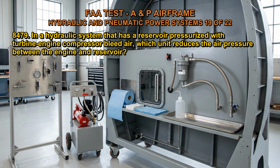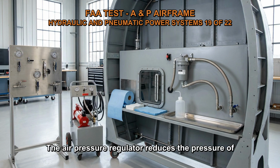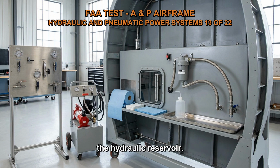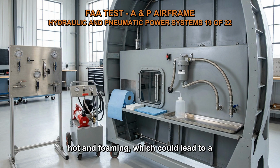8479. In a hydraulic system that has a reservoir pressurized with turbine-engine compressor bleed air, which unit reduces the air pressure between the engine and reservoir? A. Relief valve. B. Air bleed relief valve. C. Air pressure regulator. The correct answer is C. The air pressure regulator reduces the pressure of the turbine engine compressor bleed air before it enters the hydraulic reservoir. This prevents the hydraulic fluid from becoming too hot and foaming, which could lead to a loss of hydraulic pressure.